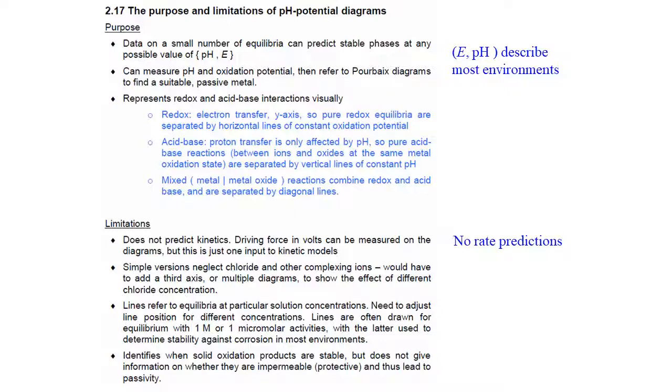In fact, zinc is often quite a good corrosion protection coating because despite the fact that there's very often a driving force for the zinc to dissolve, the other kinetic factors for zinc dissolution mean that it's a pretty slow process, so my nice zinc coating on some bridge will take a very long time to dissolve, for example. Despite corroding actively, you can calculate it's so slow that it's often a good choice for some situation. In any case, it's going to anodically protect whatever other metals you have there as well as dissolving slowly itself.